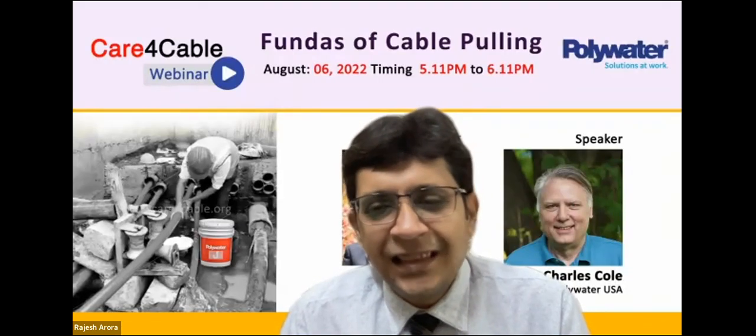Polywater has developed this software for the industry that is called Pull Planner software. This Pull Planner software is free of cost and used by many design engineers across the world. In advance, they have a theoretical tension which they want to control. So people want to control the tension or pulling force on the cable, but what is causing that pulling force is basically the coefficient of friction and sidewall pressure, and that is why the title of this webinar is Fundas of Cable Pulling. Great. That's what I wanted.